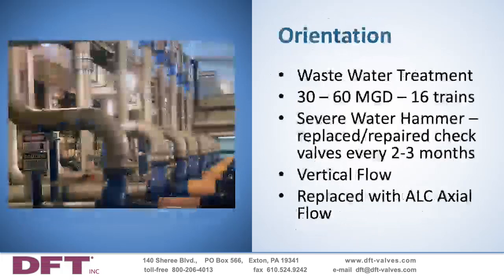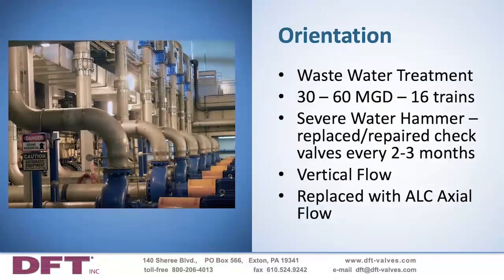Whether it's flow up or flow down in a vertical line, the axial flow check valve is very often your best solution. In fact, almost always your best solution. With pump design, a valve is often required to perform effectively while occupying as little space as possible. This is even more crucial in vertical flows where every millimeter of space is quite valuable. Axial flow check valves are ideal since they occupy less space than manual valves and other types of conventional check valves.